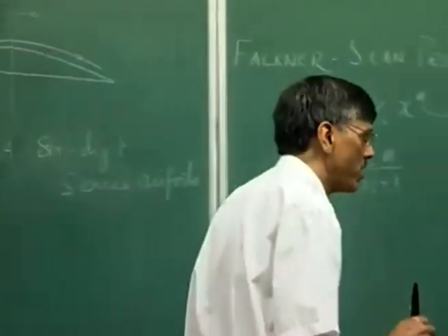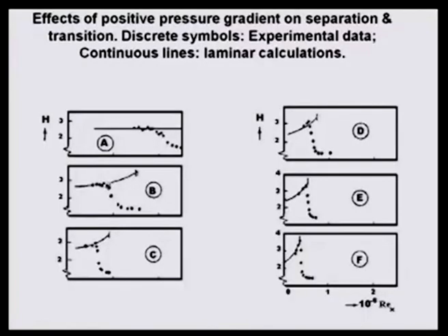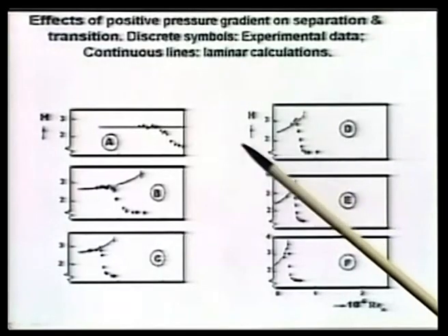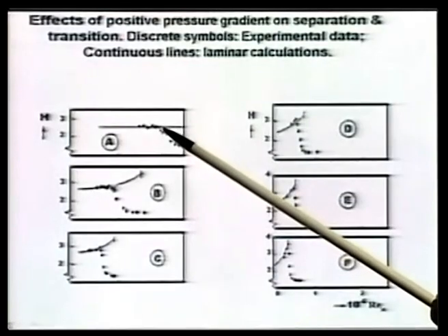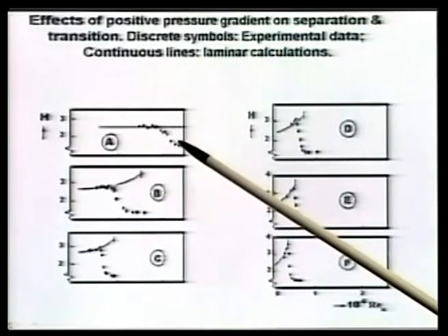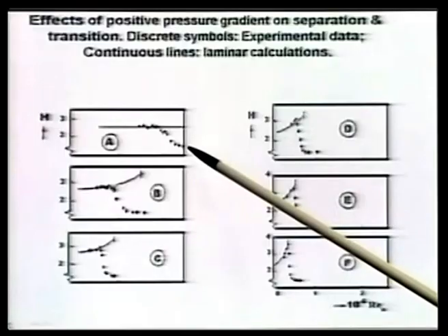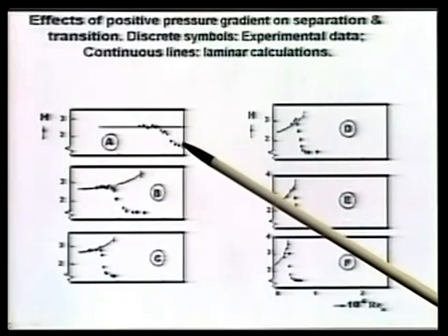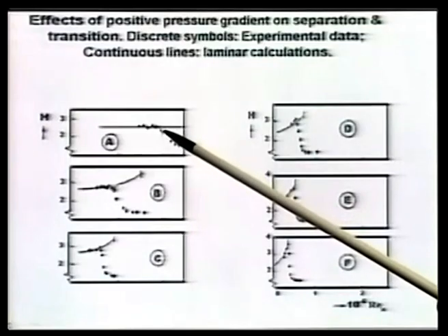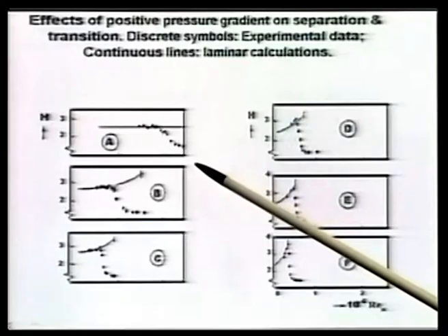As we saw in the previous frame also, if you recall, we did talk about it, that if our value of pressure gradient is not too adverse, then there is a distinction between where the flow becomes unstable. Where the flow becomes unstable, H has the tendency to fall, but it reaches that turbulent value much further down, right, much further down. So, there is this difference between the point of instability and point of transition.